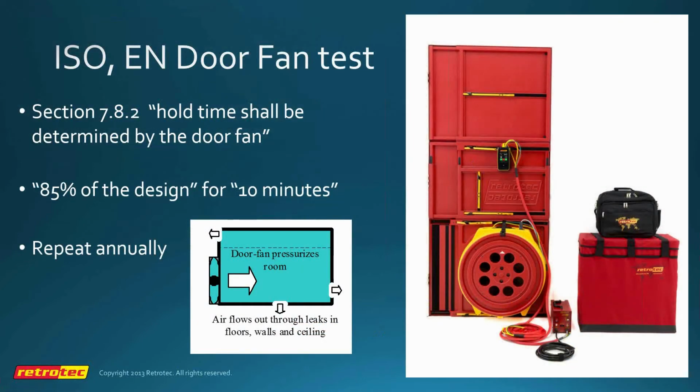Okay, so this webinar is meant to be specifically about the ISO test as opposed to the NFPA, which our past webinars have been about, and there are some significant differences. But essentially, they both say the same thing, that the hold time is determined by the door fan. And as some of you may know, the door fan test is also an ideal way to measure the enclosure leakage to estimate the peak pressure.